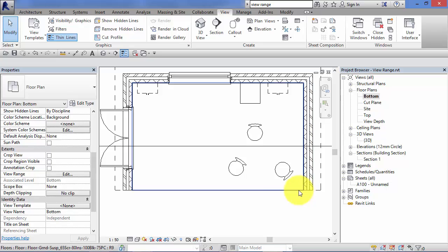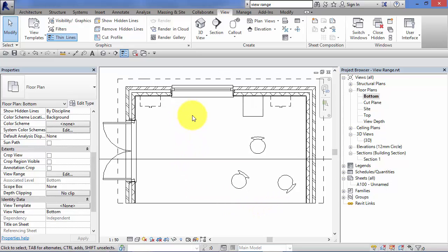Now what I mean by normal projection is Revit elements can be drawn in different line styles, and Revit controls your line styles for whether an element is cut through or whether it's seen in projection, i.e. not cut through but just seen slightly in the distance. So any elements in your model that aren't cut through but fall within that bottom range between the bottom and the cut plane will just be drawn in a normal projection line style, as in this floor element here.